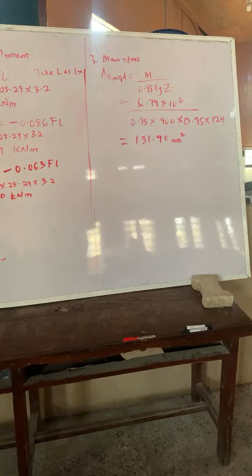Yes, normal. The only difference is that in continuous, you have to calculate for area. If it's a one-way slab, it must be a one-way slab. The third condition: in the question you will be given Qk, and it must not exceed 5 kilonewton. And the last thing is your ratio of Qk and Gk must not be greater than 1.25, it must be less than 1.25. That's all the conditions.